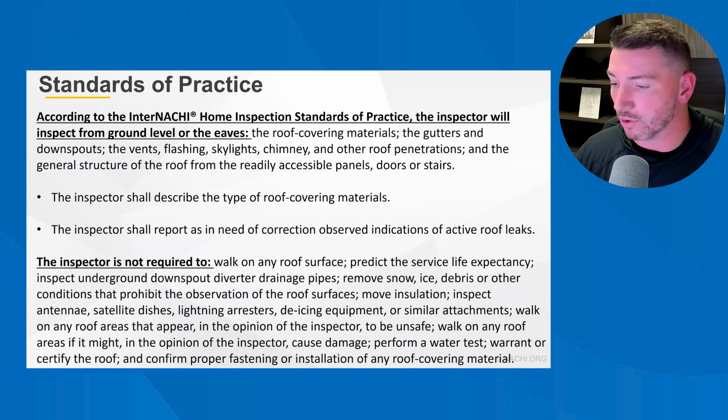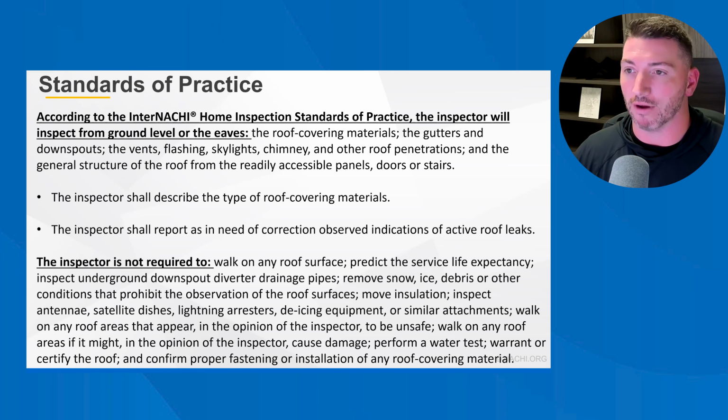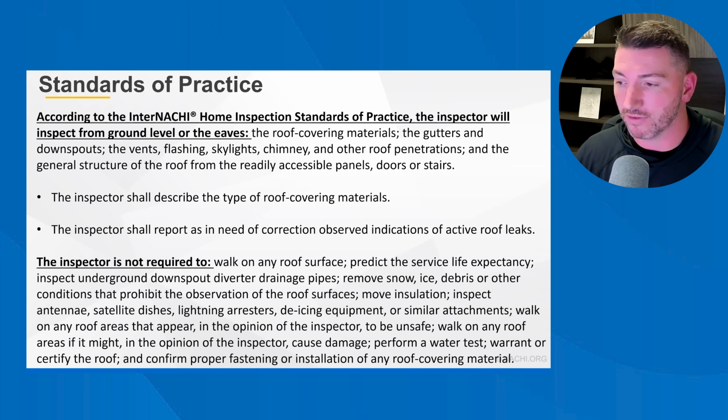And then you're not required to walk on any roof areas if it might, in your opinion, cause damage. You're not required to perform a water test. You're not required to warrant or certify the roof. That should go without saying. And you're not required to confirm proper fastening or installation of any roof covering material. So again, if it looks improperly installed to you and you're aware of why, you can obviously call it out.